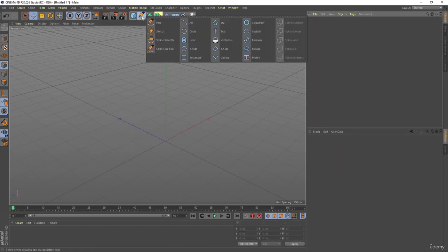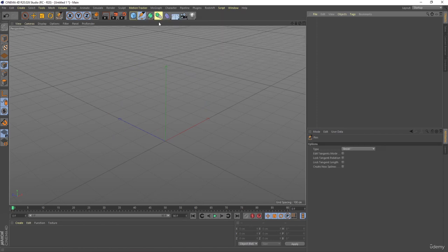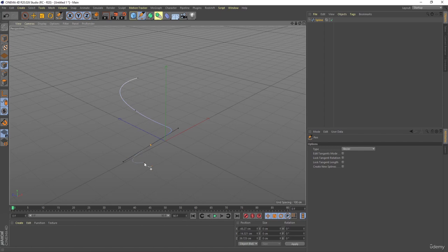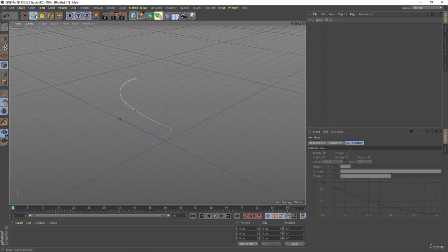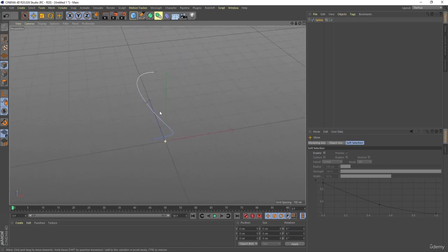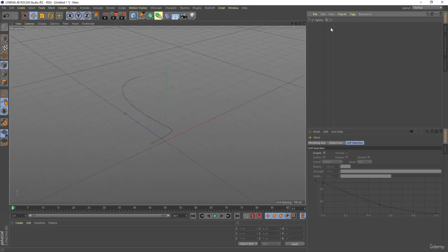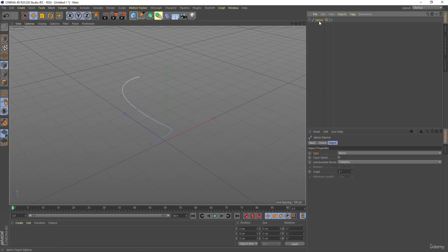Now after that there is another thing. See, suppose I select this pen tool and I want to create something like this, and I want this much spline only, after that I don't want to create any more. So what should I do? I can simply press escape on my keyboard. So now it's deselected. To deselect, choose any kind of tool like the move tool, then I'll get this spline only. Okay, so this is how you can create something like that.